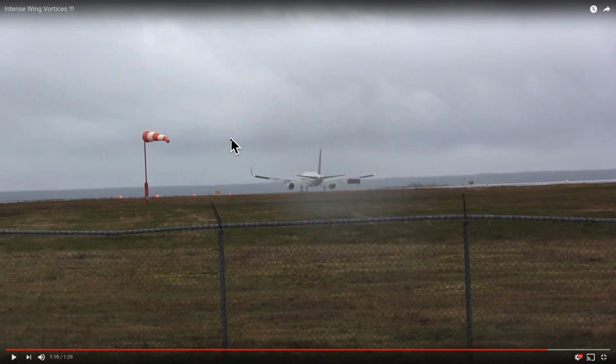I don't know if you've ever heard of the term, but you have these larger aircraft generating huge vortices of air, and it's like a washing machine. If you fly a Cessna 172 behind this aircraft at a lower altitude, even with a difference of 1 or 2 minutes between the larger aircraft and the small single prop personal plane, it turns the 172 into a washing machine and is extremely hazardous.